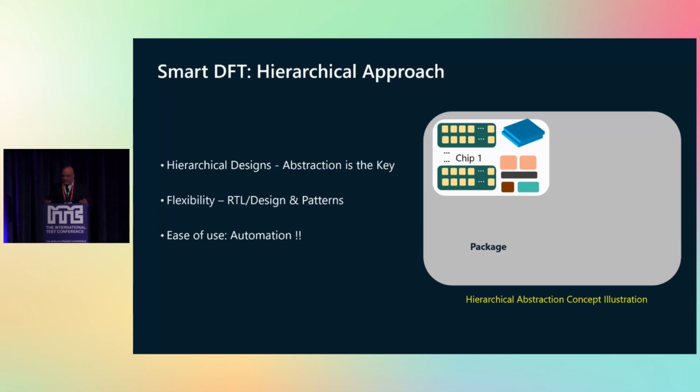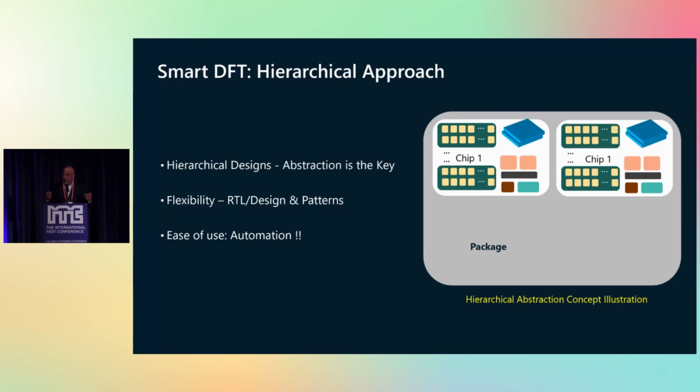Again, this is a mock-up. This is not a silicon that Microsoft designed, just to be all legal. But I'm trying to explain the concept here. Then the next problem that you face is you're reticle limited. So what this means is, in order to achieve your performance targets, you might have to replicate this chiplet multiple times.